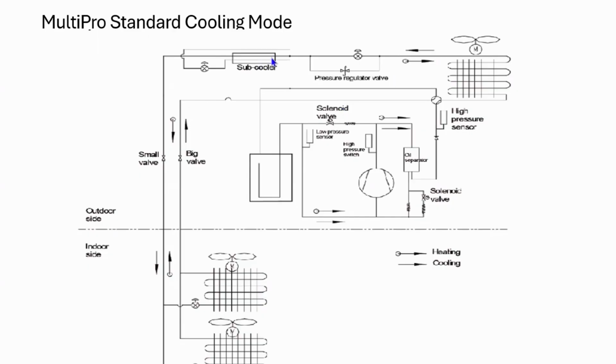Let's say I got a situation with a system where I'm intermittently getting compressor error codes. Put it that way. I was trying to find the right train of thought here. But you as the technician, every time you go out there, and let's say this piping diagram shows 2 indoor units, let's say we got 4. And you never get it to duplicate the issue while you're there.